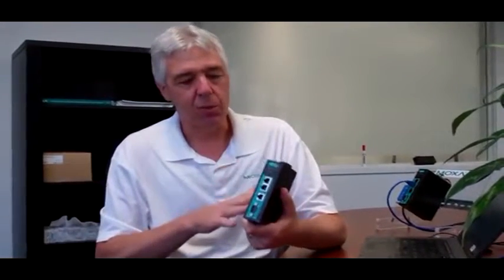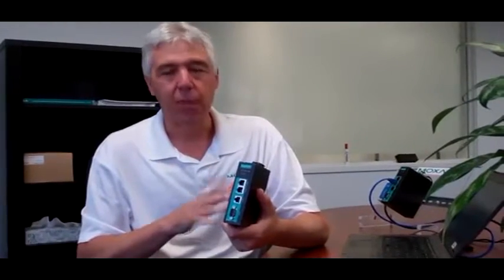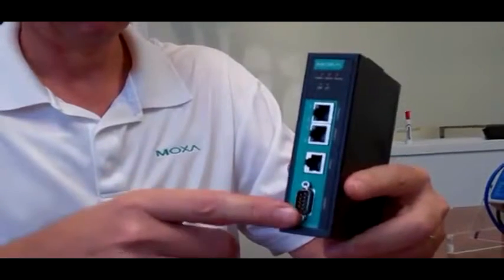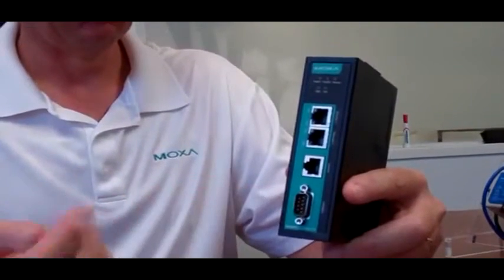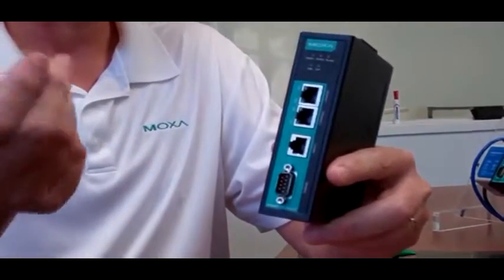And you might consider using an industrial Ethernet gateway. That looks something like this unit here. That's a small dedicated device that's self-contained and has application programs to make this really easy for you. In the case of the VFD, you've got a serial port here that connects to your VFD, and then you've got Ethernet here that connects to your ControlLogix or whatever PLC you may be using in this application.